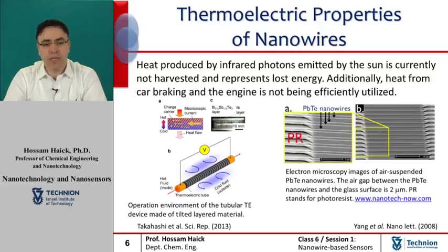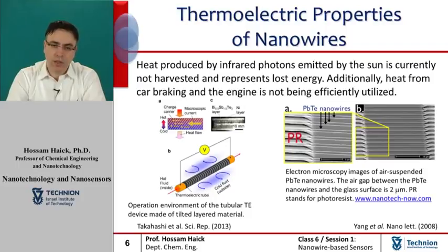In this field, it has been evidenced that nanowires have improved the thermoelectric properties, and examples for this property are given in the present slide. The left image shows that transverse thermoelectric devices exhibit distinct functions as compared to the ordinary thermoelectric devices, as described as follows. First, the voltage signal develops perpendicular to the applied temperature gradient. In this case, please refer to schematic A on the screen.